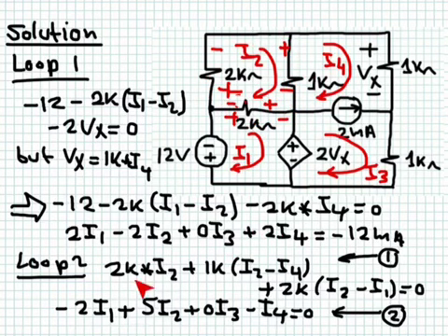So if I go in the counterclockwise direction, I obtain this expression here relating I1, I2, and I4. Remember, the current flowing here is I2 minus I4. And remember, the current flowing here in this direction is I2 minus I1. And remember, the current flowing here in this direction from bottom to top is simply I2. So I have only one equation between I1, I2, and I4, which is this equation here.